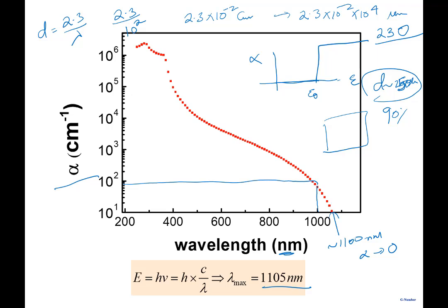So the point that I wanted to make was that I have to use very thick silicon to absorb the radiation that is falling, and the reason is the low values of alpha that you see here. The higher values of alpha, if I have 10 to the power 4, will get absorbed very quickly.